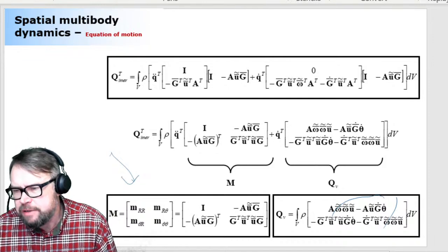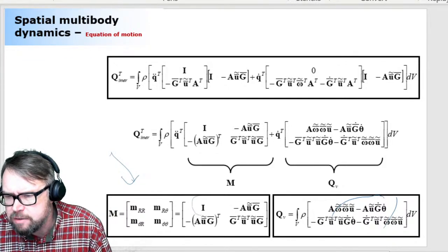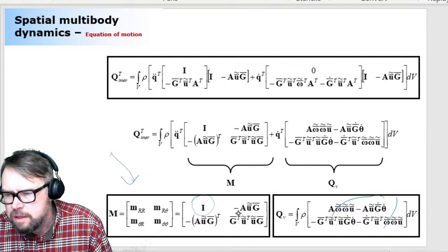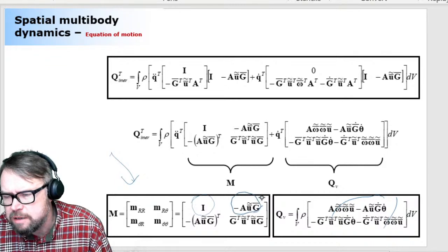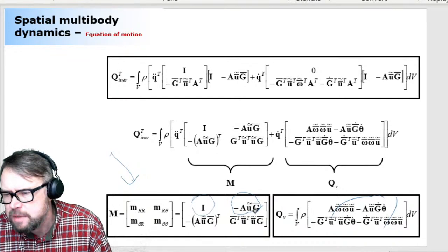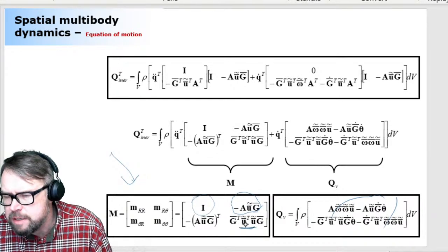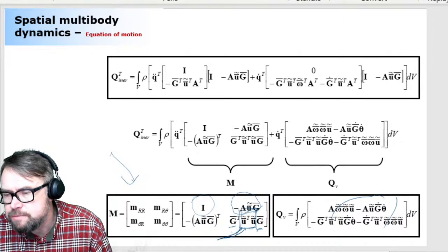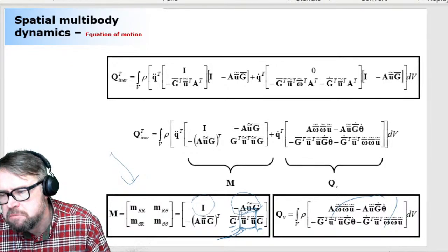Okay, what is it that I have here? I have here the identity matrix, which is a 3 by 3 identity matrix. Then I have this component that does not have a clear physical interpretation. It's the one that relates translation and rotation. And then I have here, very much in the middle, the inertia tensor, which is then multiplied by matrix T. And this is what I just mentioned to you. So this is your inertia tensor, which you can map to any configuration you want.